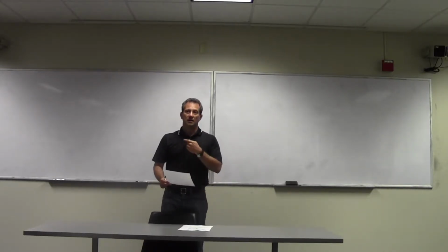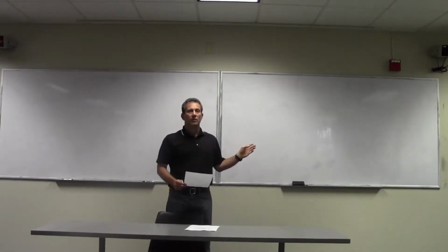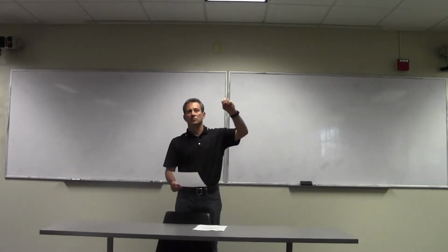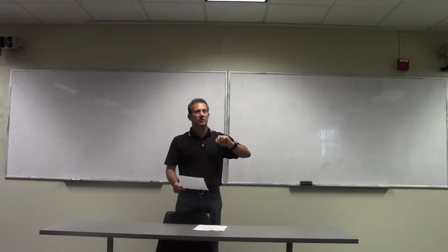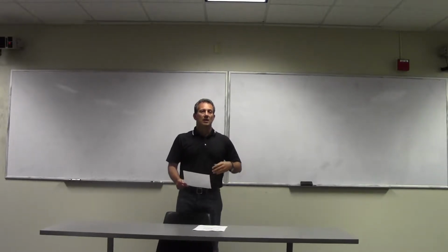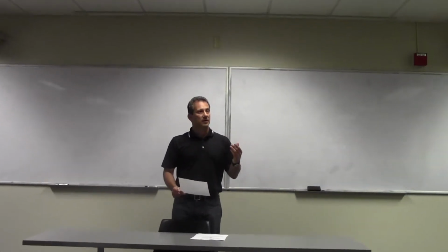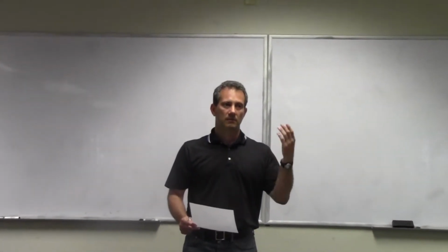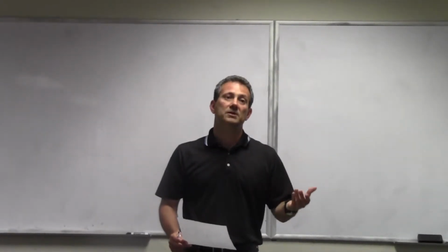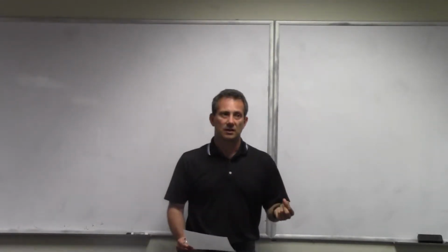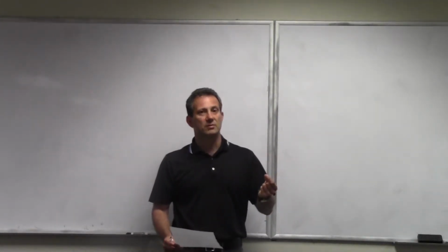When we looked at probability of error, all the formulas that we derived were based on probability of symbol error. Right? We were talking about going from S1 to S2 or S2 to S3, that you're making a mistake in interpreting the symbol. Now, we know that a symbol carries a lot of times more than one bit, right? If we have 8 symbols in our constellation, how many bits are packed on each symbol? 3.